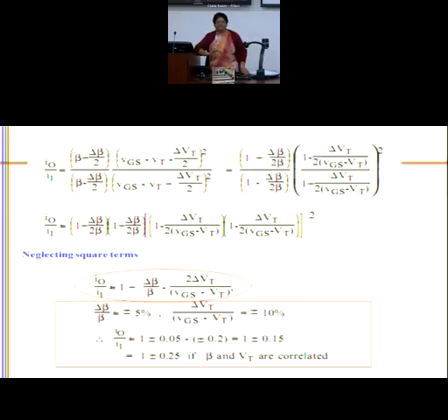So the maximum deviation that you can obtain, you can compute by using this relation. This is known as a mismatch analysis. I know that even if I take huge care in the schematic, process variations are something I cannot have 100% control over, so I am going to get a variation. So we say let process variations only have a say on mismatch.